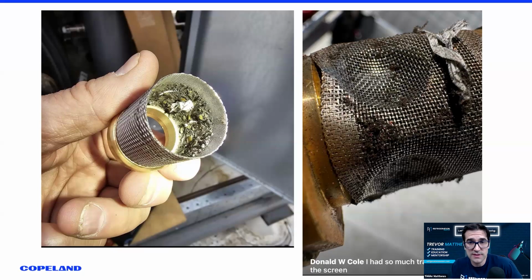That gas cooler out sensor that he talked about, the receiver pressure sensor, the ambient sensor, and the temperature probe. You actually have to do the test. Have the high pressure gauges. A lot of times there's an analog gauge on there, and these are the verifications you have to do almost every time.